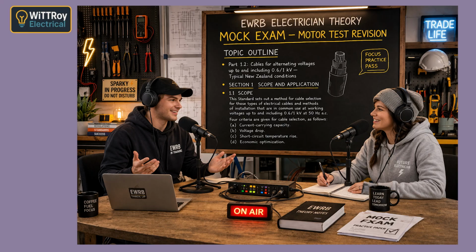Yeah, this part definitely needed more detail. It did. From question 14 onward, a lot of them are system behavior questions. If you only memorize a sentence, you can still get tricked. I can see that. It's more like one thing causes another thing. Exactly. Capacitors change reactive demand, unbalance causes neutral current, low voltage affects torque and current, overload affects heat, and phase sequence affects rotation. It's all connected. That helps a lot more than just hearing the answer. Good. That's what revision should do.